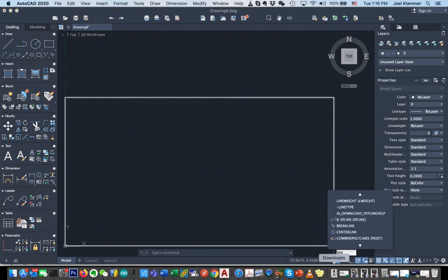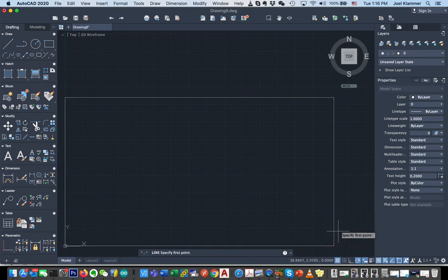Line. The problem is switching back and forth. Line tool. There. Start dragging it up. You'll see the extension. And I want this to be 9 meters. So I'm just going to type in the number 9 and press Enter. And immediately it jumps up to here. And now I can start dragging across. You'll notice it actually has an angle on here. But it also has a nice little right triangle saying, hey, yeah.